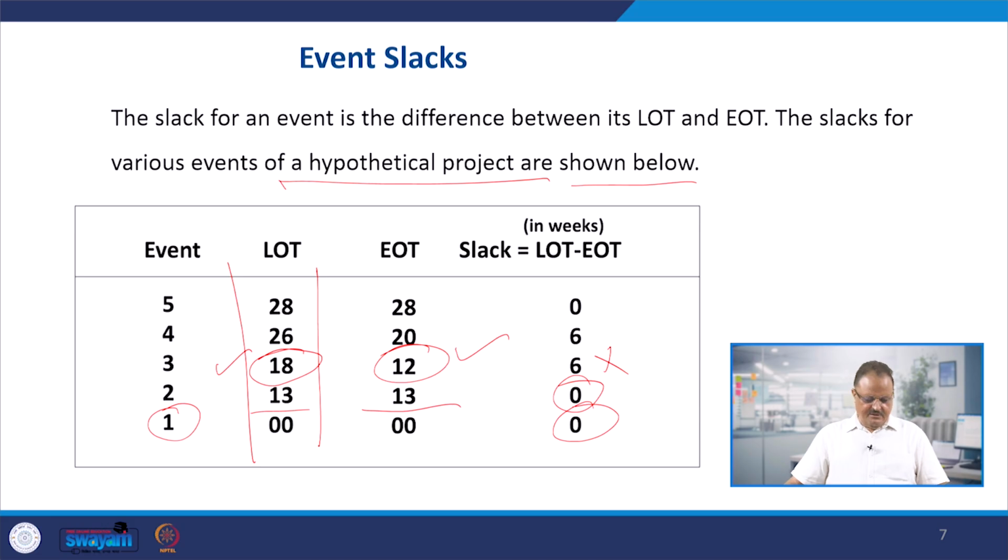But the relationship between the direct cost and the duration is an inverse relationship. If you increase the duration, direct cost will go down, right? But if you reduce the duration of the project, direct cost will increase, because you have to employ more resources. You have to bring more material, more workers, more power, everything more.